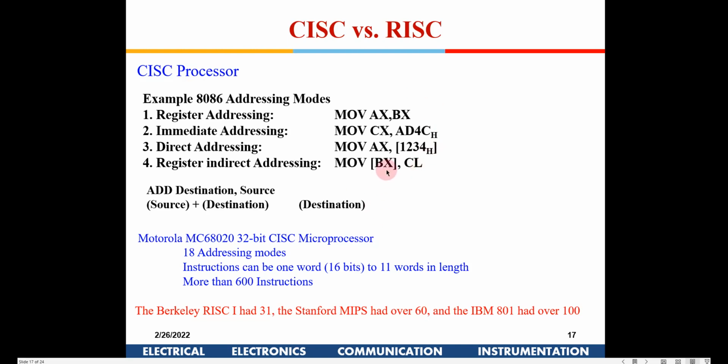Now this becomes even more complex. There are instructions in which you can write MOV [BX + 100], CL. In that case, the data available in CL is stored into some memory, and what is the physical address of that memory? The offset is given by the contents available in BX plus 100, and then again you will have to refer to DS to generate the physical address.